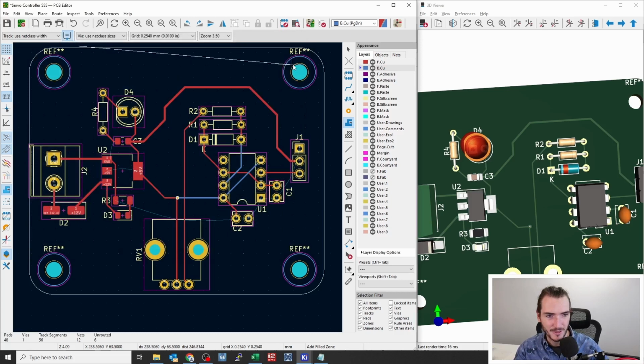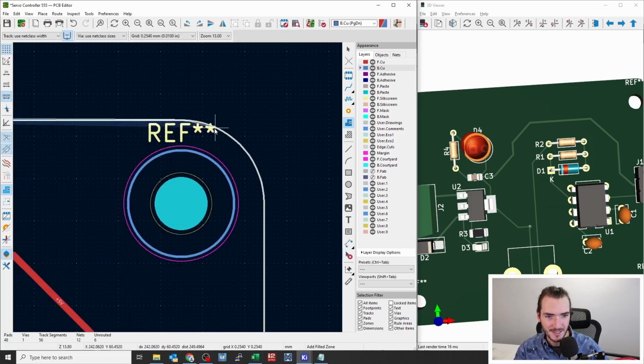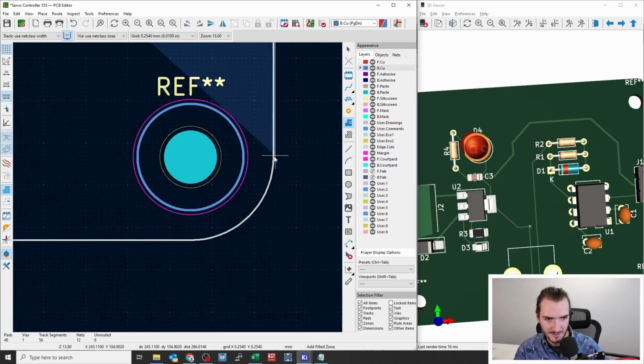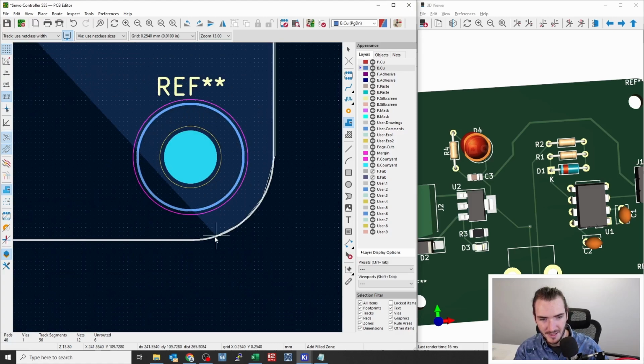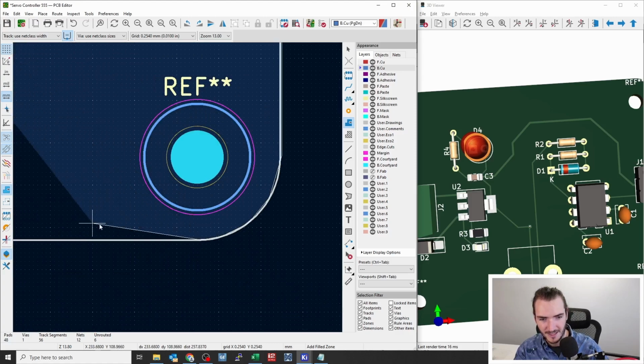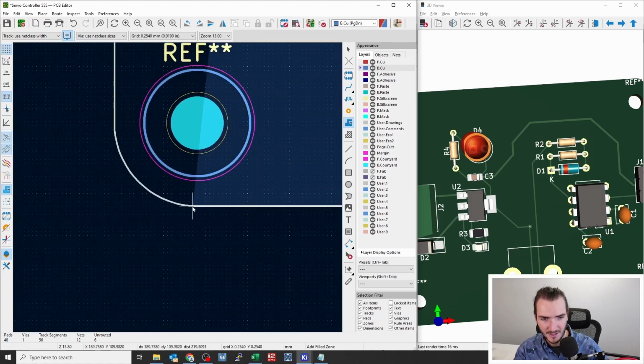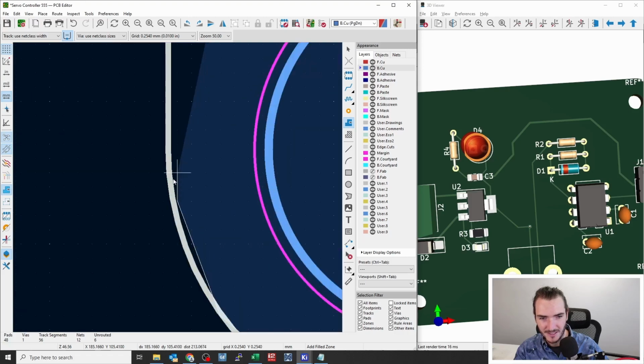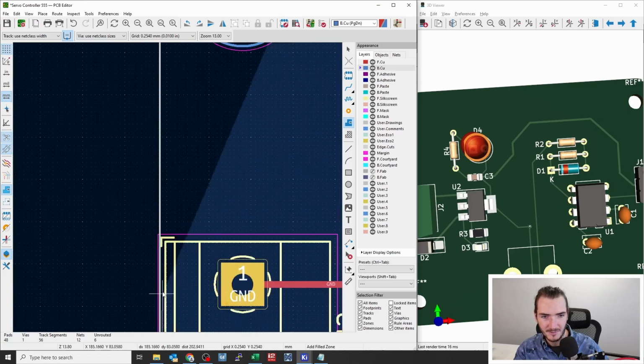And now I'm drawing a polygon. So I'll keep that as best I can to the outline of my board. We're drawing this closed shape. It is best practice not to go too far outside the bounds of the board for manufacturing reasons that you might come up against later. So I like to keep mine within the stroke, if I can, of the edge cuts. A little bit outside is okay.